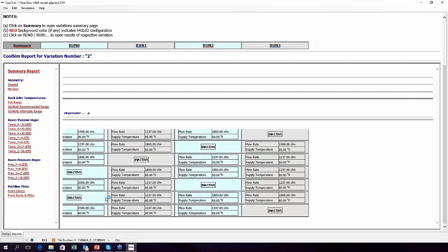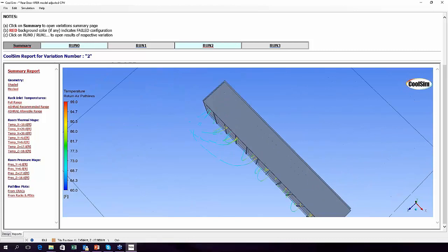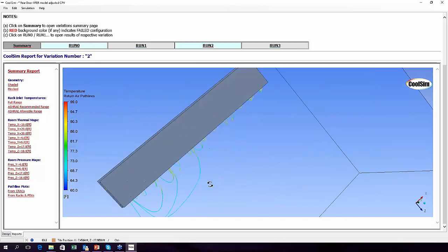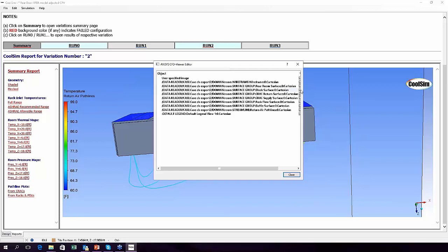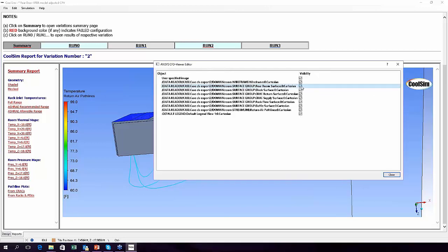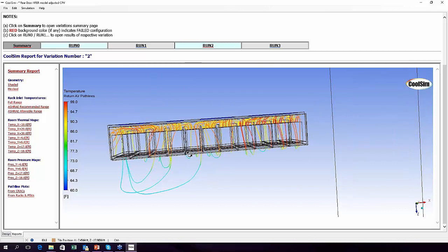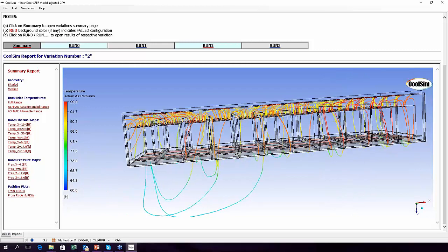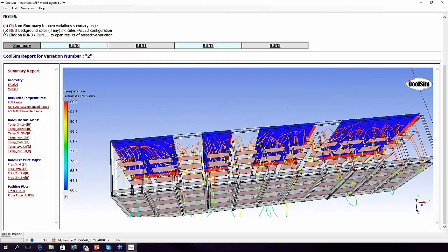So the way we did it is to take a look at the case where they fail, and you see they're starting to wrap. These are path lines from racks. Let me get this around, and let me use the E key to shut off blocks so that we can see inside there. So let me just turn off the room again and turn off the blocks again. And you see what's going on is the air is going around. Some of it's going through the cooling unit, but there's also some going around those rack rails to the front.